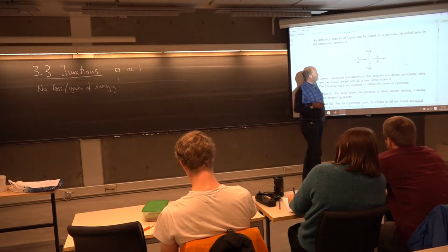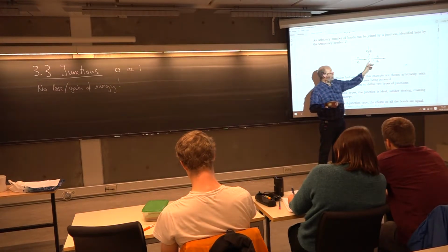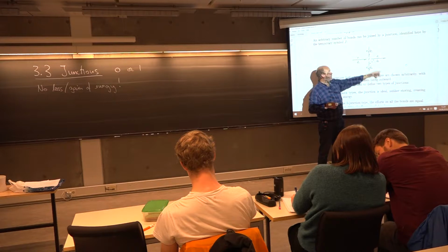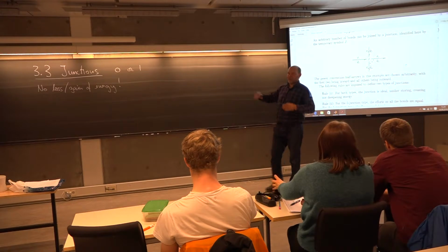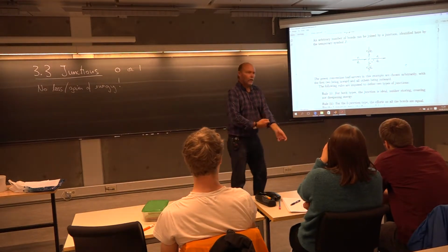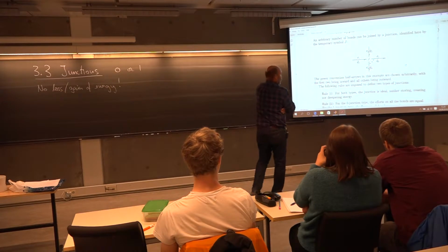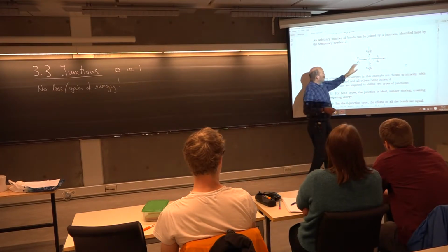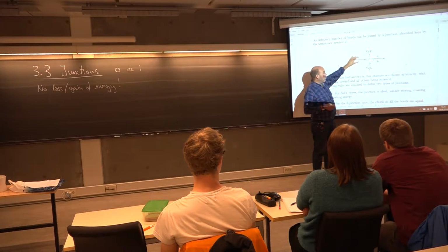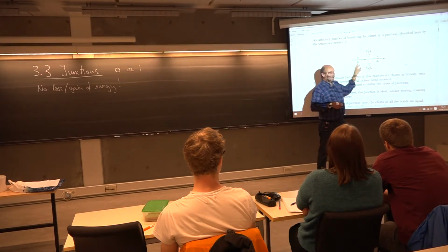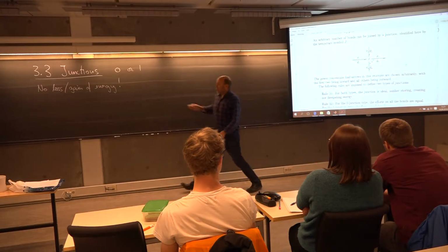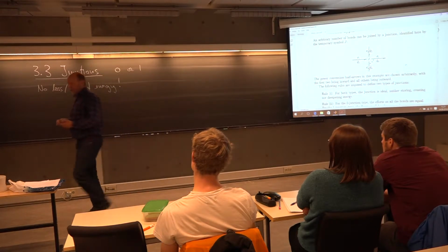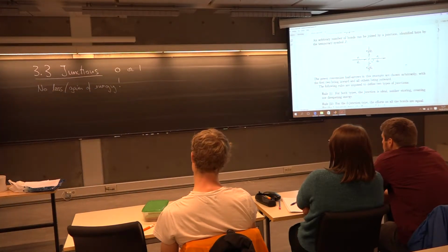So that means when you have a junction, he can combine many of these power bonds. Some may go in and some may go out of this junction. The direction there, that's up to us. What we mean is a positive direction. That's not so important. But what is important is when you make a sum of all the powers entering and exiting, you will always get 0. So no loss, no gain of energy. That's the important part.